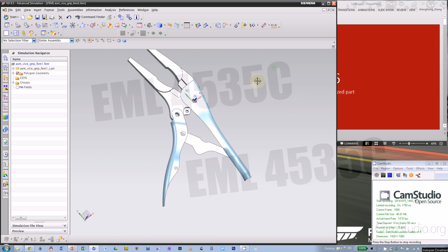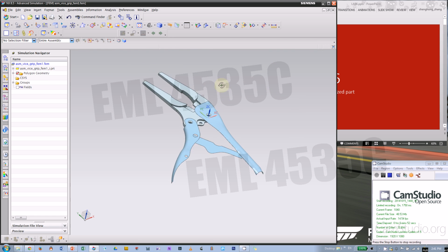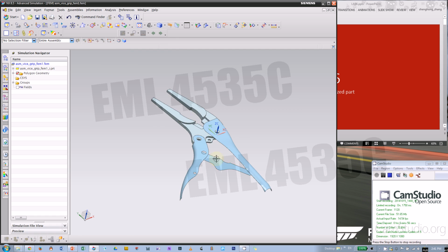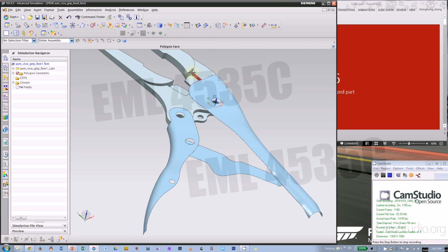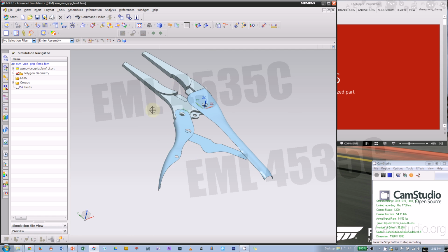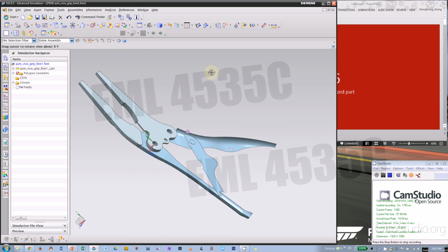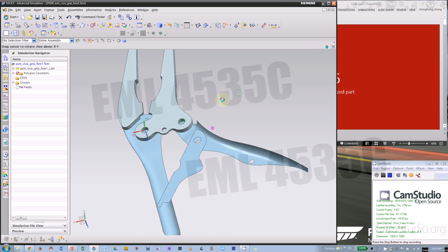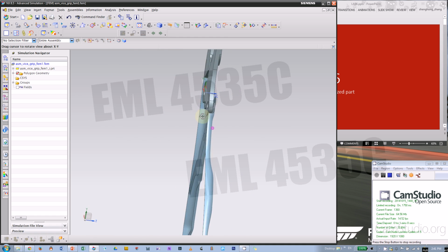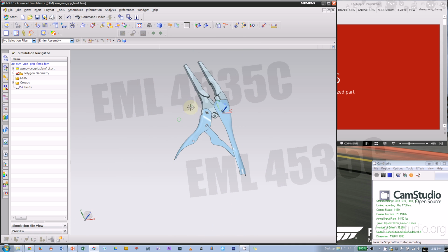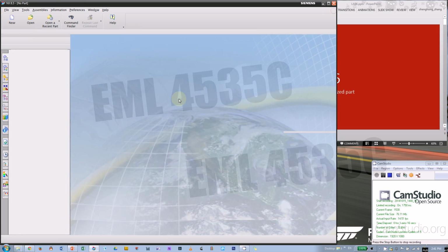Okay, so that's the midface for the shell body and for the shell mesh, and those are the solid for your 3D tet mesh. And also the whole model is only a half. Then we're going to reflect it to the other side to make it symmetric.